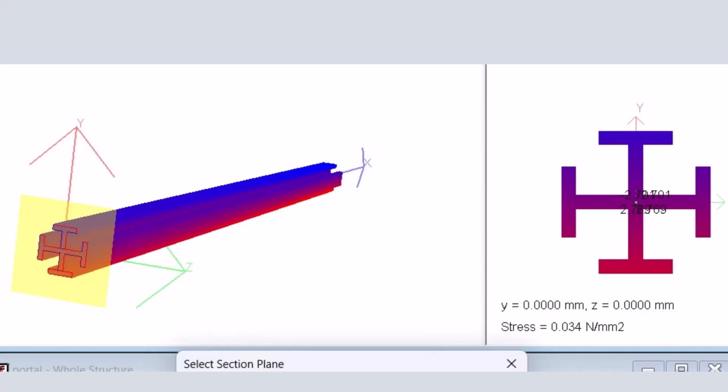We had also discussed how normal fiber stress are displayed for those complex cross sections. We also touched upon the challenges involved in designing such non-standard sections. As discussed earlier, there are certain limitations in directly designing non-standard sections using the codal provisions. However, these sections can still be designed by treating them as equivalent I-shaped sections using Indian code, AISC code, or equivalent standard profiles using the Eurocode.